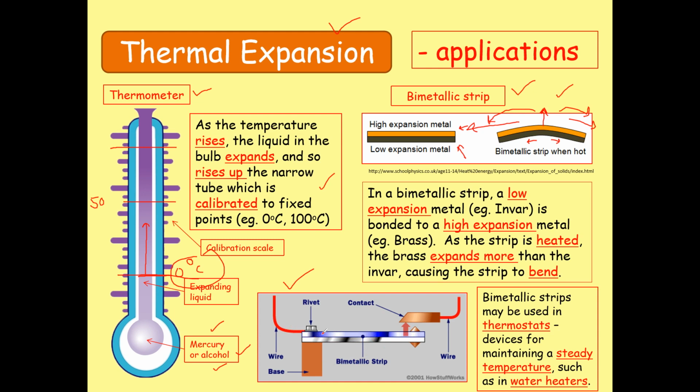Why does it turn off? Because at a certain temperature, depending upon the setting that we're using, this bimetallic strip is going to bend downwards, right? Since one end is riveted and the other end is free, the upper strip will expand more and the lower strip will not expand as much, so we will find that it would turn downward. As a result, this contact will be opened, right? So at a certain temperature, this bimetallic strip is going to break off from the electric contact. As a result, electricity will stop flowing, and no more heating would be there, so it will prevent overheating of the iron. Hence, you're not going to burn your clothes while ironing those, right?